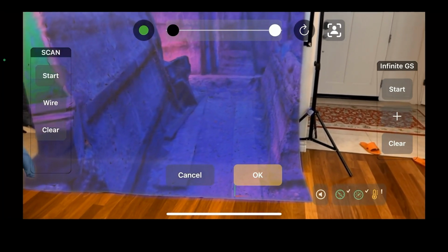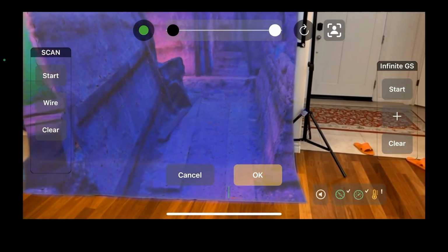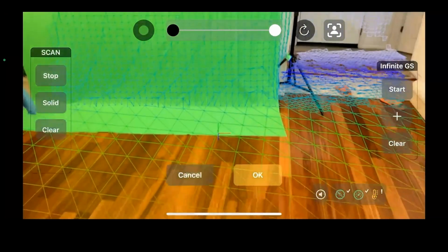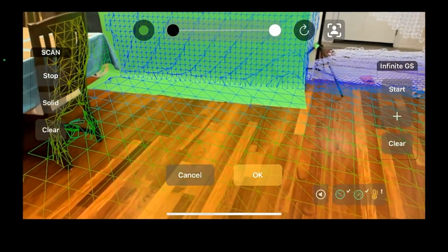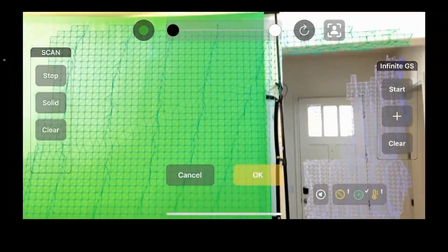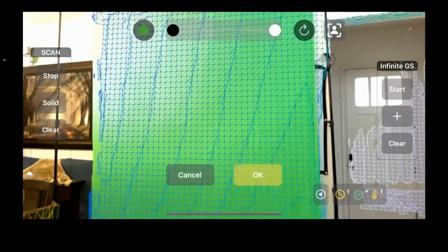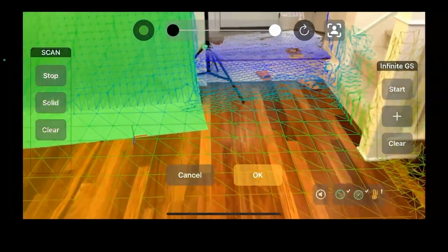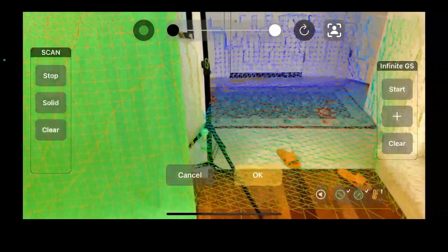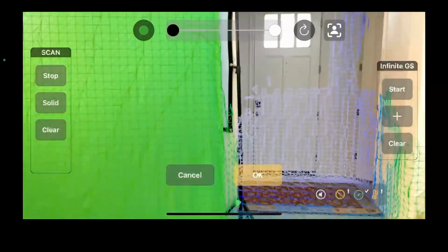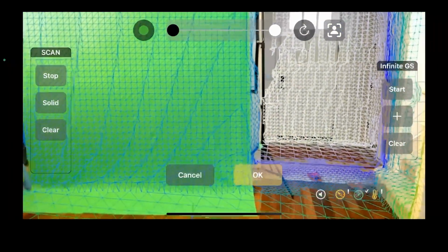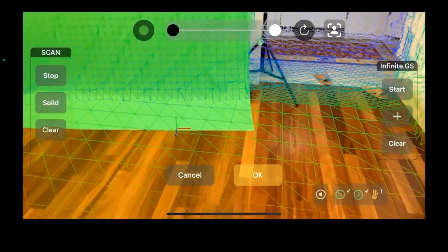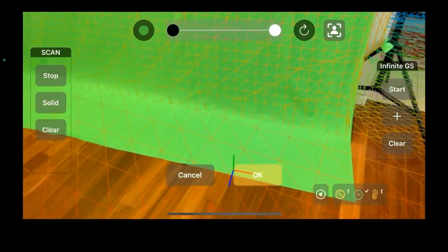If you can, you always want to do a scan of the physical area before you're recording. So we're going to click Start, and you can see immediately it's using the onboard LiDAR scanner to very, very rapidly map some geometry onto the surrounding area. There's a little chair over there. There's a little floor, back wall there. Okay, and so it does a very quick, kind of a rough scan of the area, and we can come up a little bit closer and it'll get a bit more fine-grained.